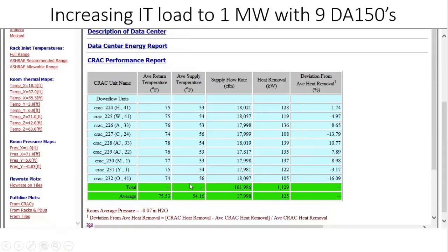They're using a performance data boundary condition, which uses a thermostat, which on these units actually sits in the return, set at 75 degrees, which is a normal configuration for a convective room return kind of design. So with the 75-degree thermostat, you see the return temp is 75 degrees. Supply temp here is in the 50s.